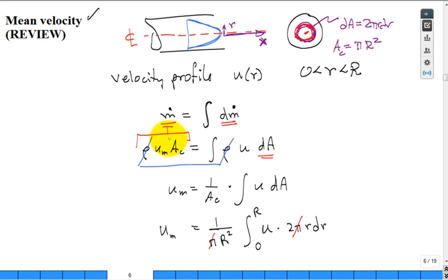All right, we cancel the rhos, and then we have the definition of u sub mean is 1 over A sub c times the integral of u dA. It's the area averaged velocity over the area of the pipe. That's what that is. And so somebody says, oh, I forgot, from calculus, what is dA? It's 2 pi r dr. Does that flow off your tongue pretty easily?